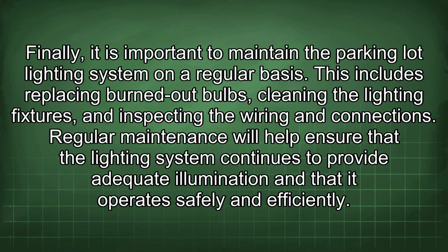Finally, it is important to maintain the parking lot lighting system on a regular basis. This includes replacing burned-out bulbs, cleaning the lighting fixtures, and inspecting the wiring and connections. Regular maintenance will help ensure that the lighting system continues to provide adequate illumination and that it operates safely and efficiently.